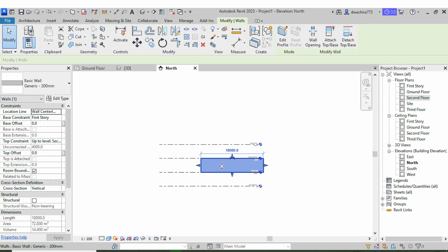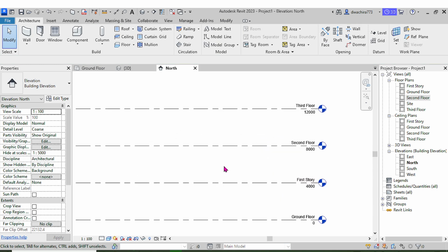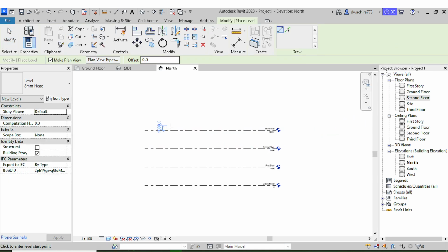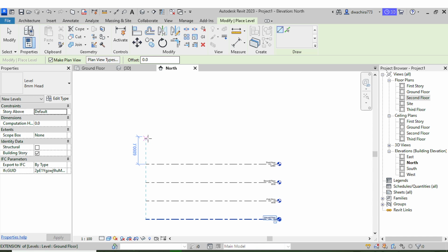So that is it. We can just proceed and delete this particular wall. Now, the next thing that we need to note is that when you are creating these levels, if you note carefully, we are clicking at this particular level at this point, and then you proceed and click to start placing. Now, if you want to have a building that has 20 floors, that of course will take a lot of time, and there is a way that we can reduce the time taken by using the copy. We are going to look at that very soon.